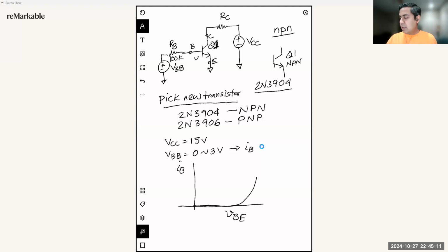The voltage we are more concerned about is the voltage between the base emitter junction, the VBE voltage. To get that voltage, you need to change the x-axis of the plot. Once you plot the current IB, by default this voltage will be VBB, but you need to change that to VBE.